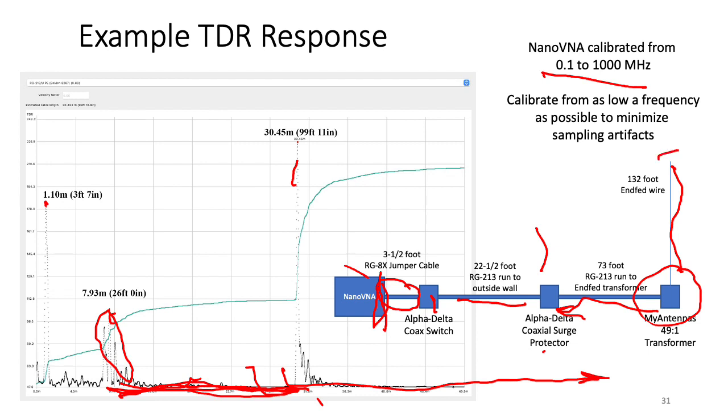And of course, the velocity of propagation here is quite different than it is in coaxial runs. Here I'm looking at a coaxial cable propagation factor of around 0.66, whereas in a piece of wire, I would see a propagation of 0.95 the speed of light or so.